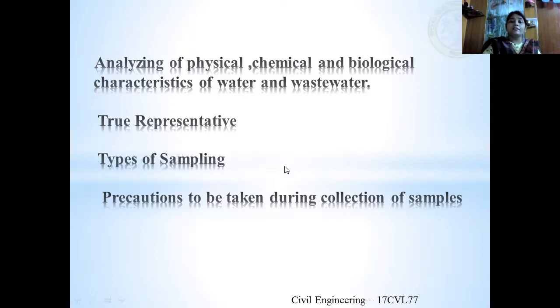Then the sample, when it is collected, in case it's tap water, it's borewell water, the water has to run for a few minutes. Then the sample has to be collected. You have to clean the tap, collect the sample, see that the water enters the bottle directly. It doesn't come in contact with anything outside, with the atmosphere, with the dust particles, even with the hand of the person who is holding the bottle. Immediately after collection, you need to close it with a lid, with a stopper, and take it to the lab